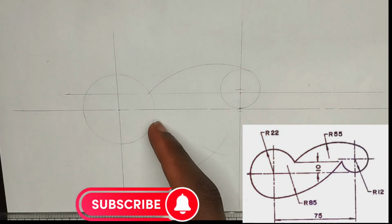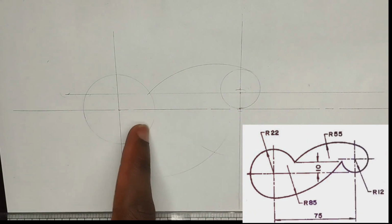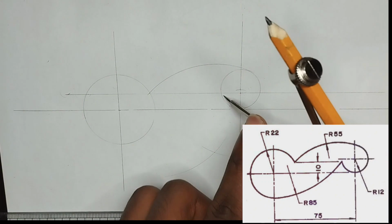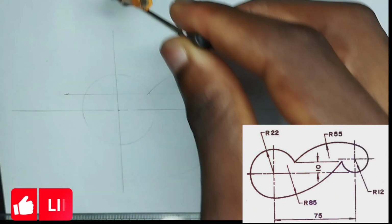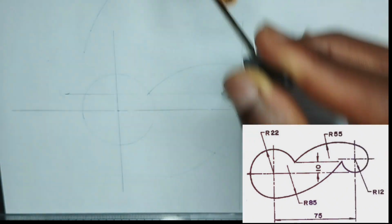I've also been given another arc which is joining these two particular places together, which is of radius 85 millimeter. So using the principle of arc from a point first, we are going to pick 85 millimeter on our compass. I'm going to be placing my compass at this particular point and then striking an arc in this manner like this.